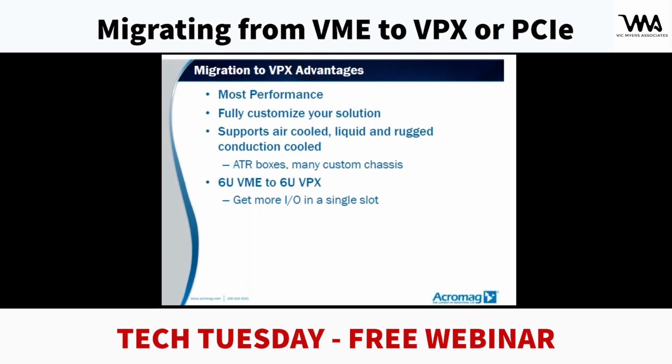Also, from a system packaging and environmental standpoint, VPX offers air-cooled, liquid cooling, rugged conduction cooling in the form of ATR boxes, which are air transport racks, and other types of custom chassis that allow very high-end performance. 6U VME to 6U VPX, we get more I/O in a single slot with the 6U VPX as compared to 6U VME.